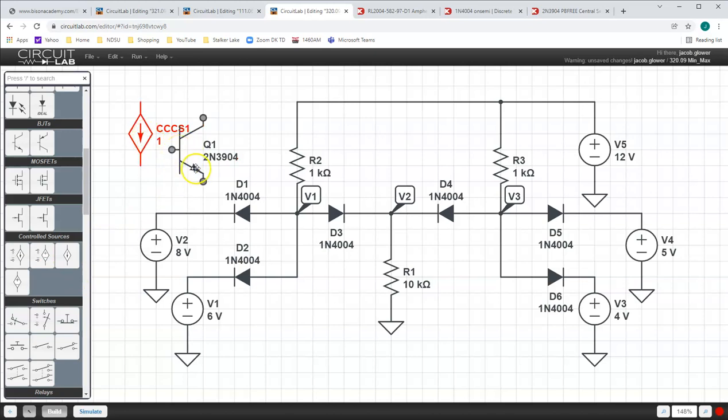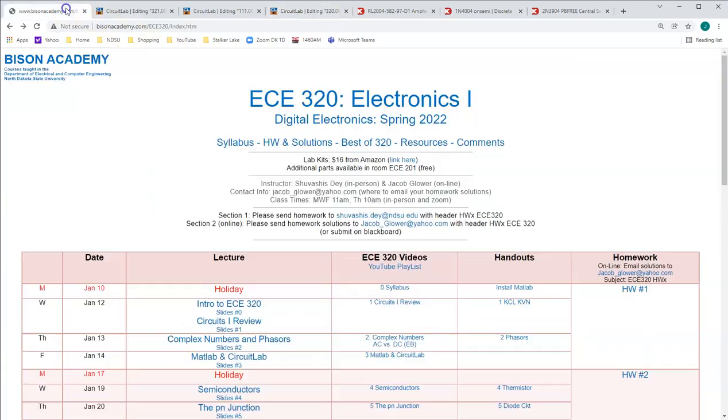It's nonlinear because I have a diode in it. It allows current to flow one way but not the other. And the current then gets amplified up to a limit. If my power supply can only output 100 milliamps, this can't amplify the current more than 100 milliamps. That gives you another nonlinear element. So electronics is all about analyzing circuits with nonlinear elements, and that's what makes it hard. I'm now dealing with solving nonlinear equations.